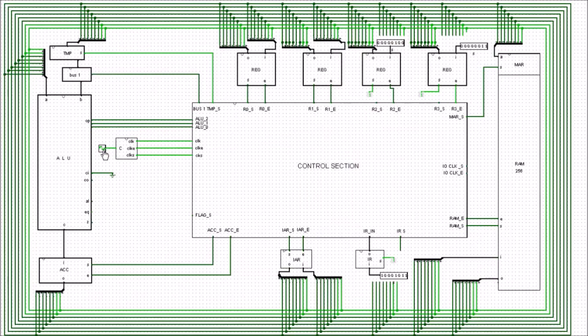So we're looking for the next clock pulse, enable going high. So that's our enable gone high, and you can see here and there that enable's gone high there, and it's put the value 1, 2, 4 onto the bus, and that value will just come along and it will drop down into the ALU here.